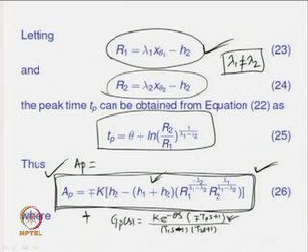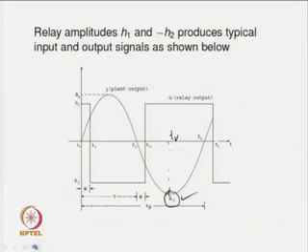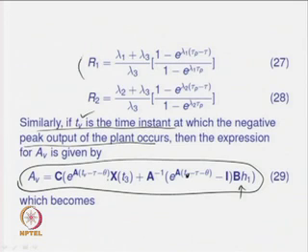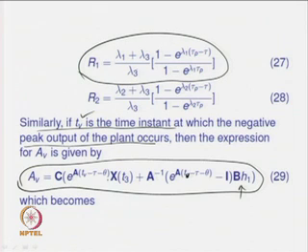So, when the expression for x theta 1 is substituted and simplified, that gives us R1 equals H times (lambda 1 plus lambda 3 upon lambda 3) times (1 minus e to the power lambda 1 tau p) minus tau upon (1 minus e to the power lambda 1 tau p), and R2 becomes (lambda 2 plus lambda 3 upon lambda 3) times (1 minus e to the power lambda 2 tau p) minus tau upon (1 minus e to the power lambda 2 tau p).